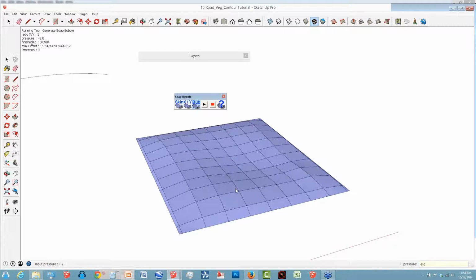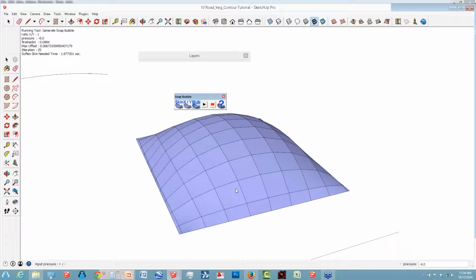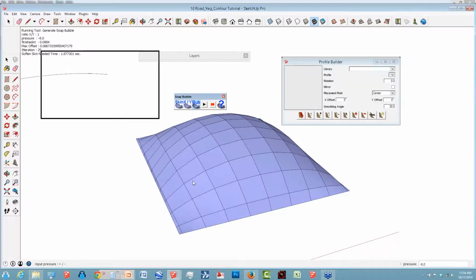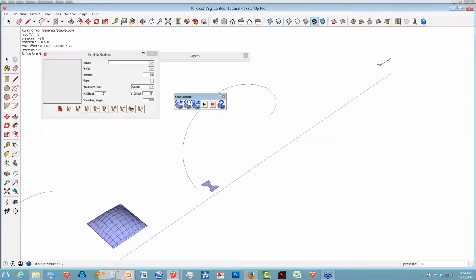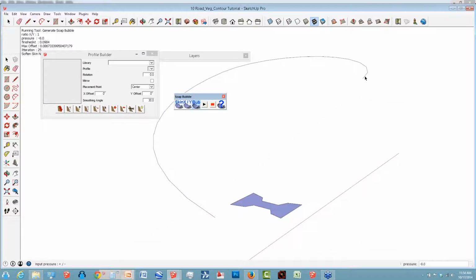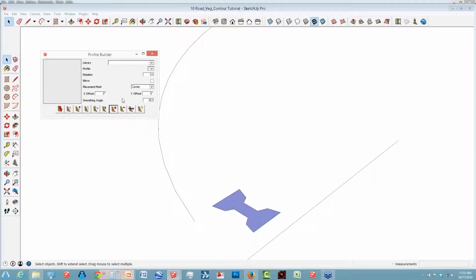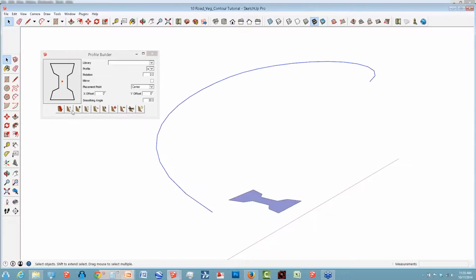There's one more thing that I want to do, then we'll open this up to questions, and that's to show one more plugin. It's called Profile Builder, and this is by far my current favorite because of what it can do, and it's really simple in what it does. Here I have a sloping set of arcs, right? I can select this profile that I drew, click the plus button. I can now select this curve, and using Profile Builder, it will quickly allow me to extrude that really simple object along this